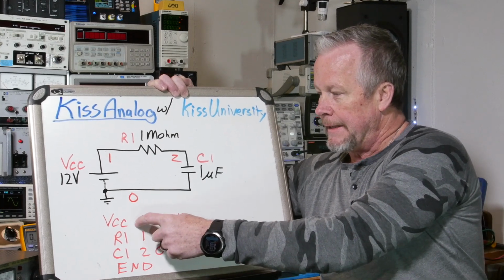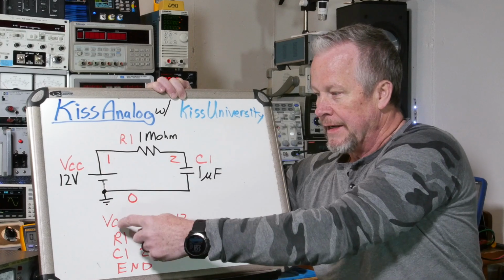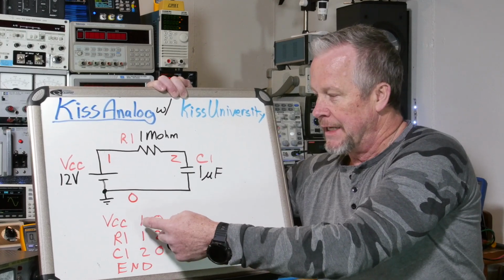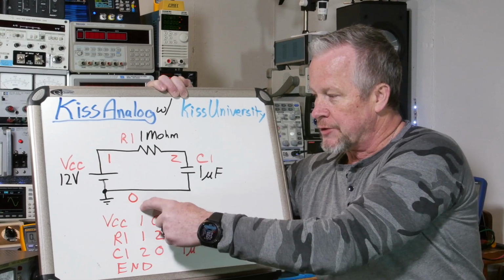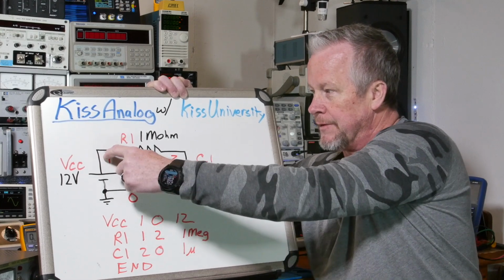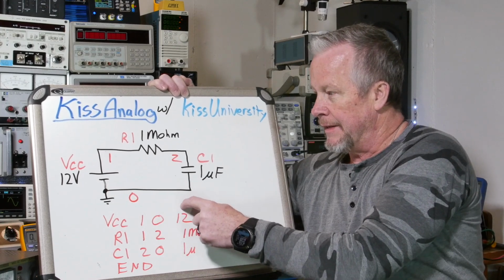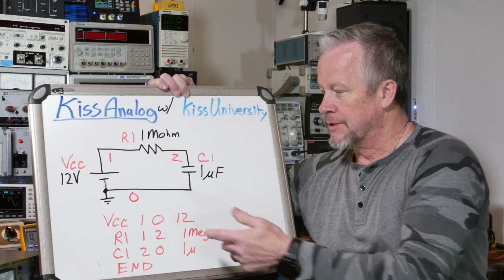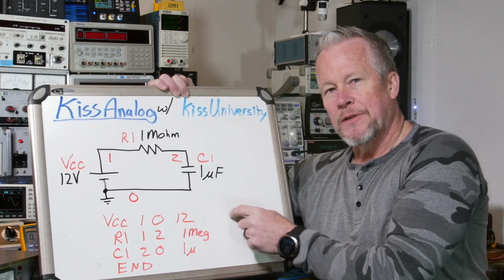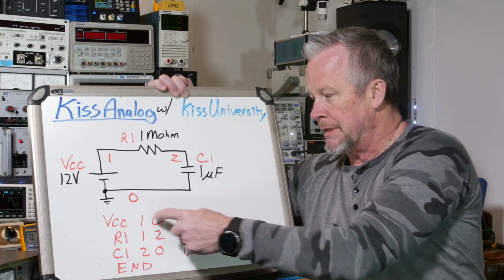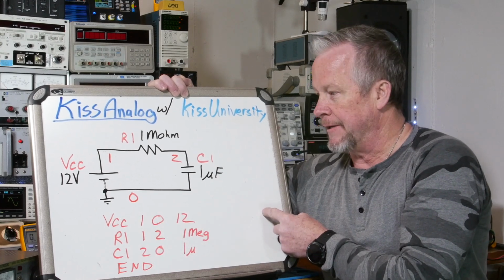The VCC, first you'd call it V, and then it could be called anything, but say CC for instance. And then this first place would be this node, and then this node, and then this value. And then there might be some other things that you could put in there, like temperature, things like that, but you'd put the syntax down like that, okay?